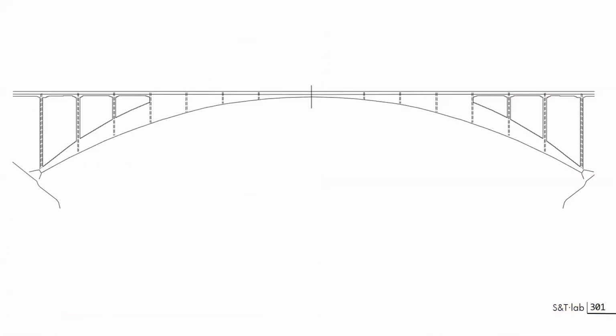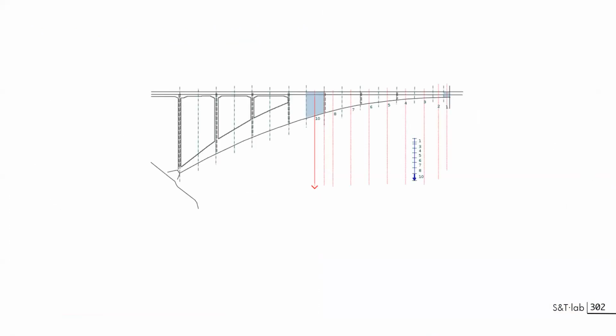So this is the bridge that you know already, and you will see it first for analysis purposes. I will be discussing design just after. So for analysis purposes, I will be slicing this bridge and calculating the corresponding loading of each of these slices and start building a load line. The load line is here, and I will start building a first funicular polygon acting in tension by just deciding that I will use side rays that will have an angle of 45 degrees, and that will help a lot for the solving thereafter.